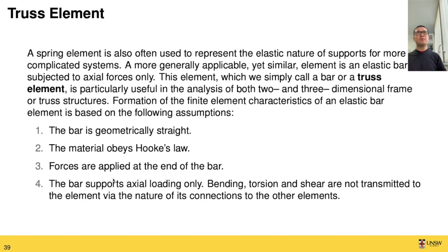And the bar supports axial loading only. By that we mean that if we apply a force to the element, it only goes along its axial direction. We are not twisting the bar such that it will start to have rotational motion within the bar. So those forces are not allowed in the bar.